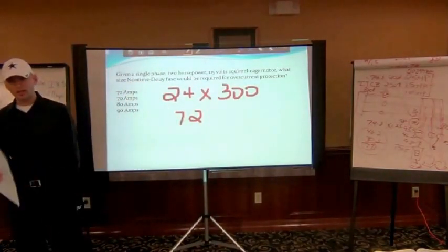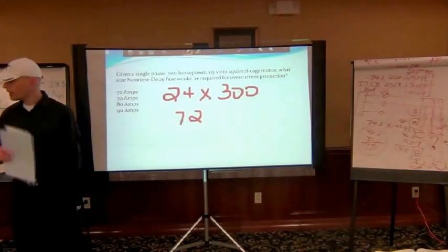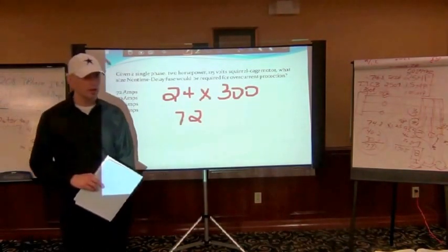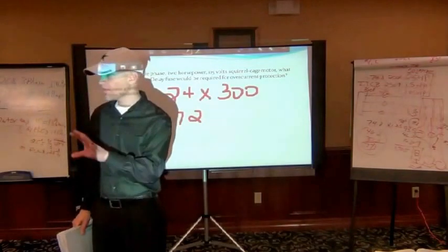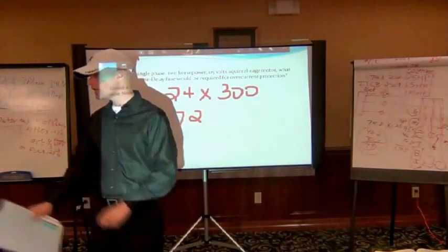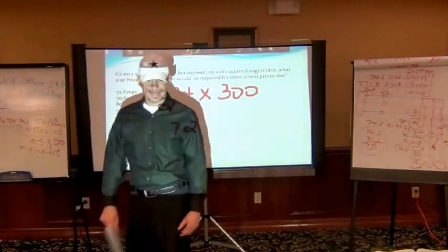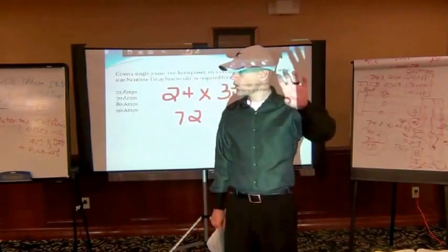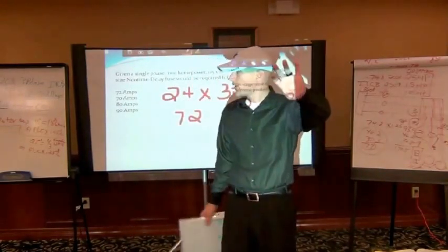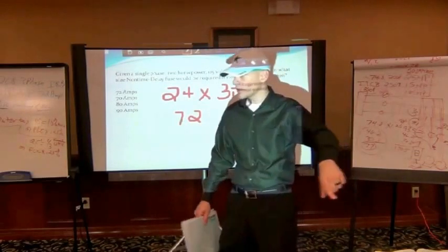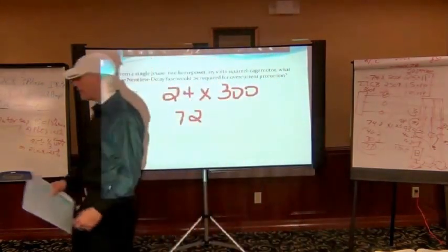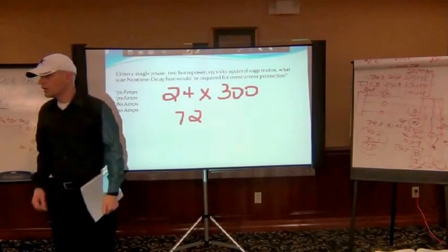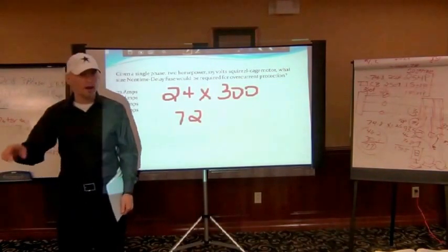Now, it sounds like a lot to keep track of, but after you do a couple of them, it's really not. Wire size is either going to be 125%, or if it's a different duty, it's going to be that table there, and that's it. If it's a multiple group of motors, then it's the largest motor times 125%, or if it's other than continuous duty, whatever the value on the table is, plus the sum of all other motors. That's it. If it's wire, it's right there.